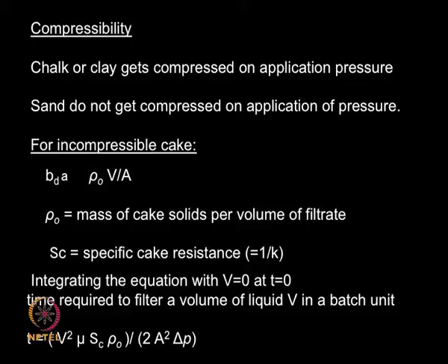So when we assume the solids are incompressible, that means there is no change in the porosity if I keep increasing the pressure across the bed, okay. Then we can say the bed thickness as a function is equal to rho naught. Rho naught is a term which is defined as mass of cake of solids per volume of filtrate multiplied by V, the total volume, divided by the area.